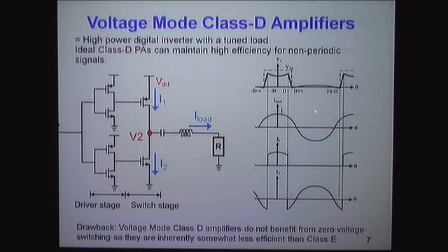So here you would look at the waveforms associated with it. This is very simple. It's sort of, let's say, a square wave voltage generator, although it could be pulse width modulation. So you look at the upper and lower. And of course, because this passes through a filter, basically what you are doing is you are generating one portion of the sine wave with the upper transistor and the other portion with the lower transistor, and you get to fill it in.